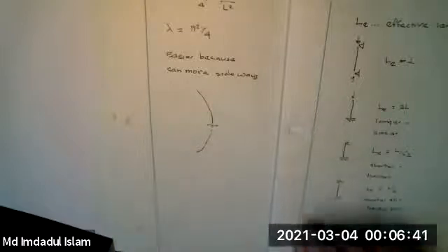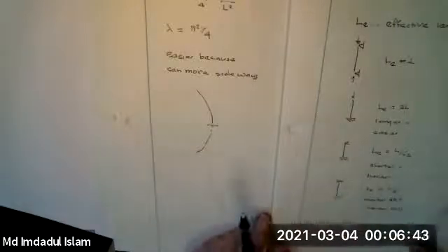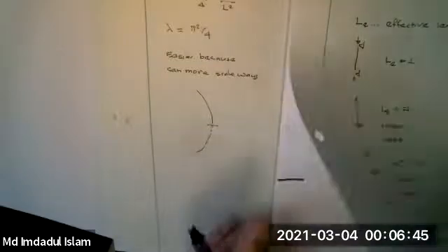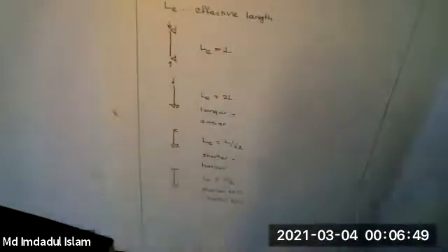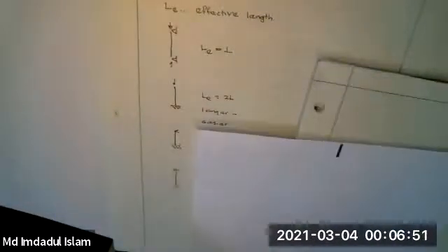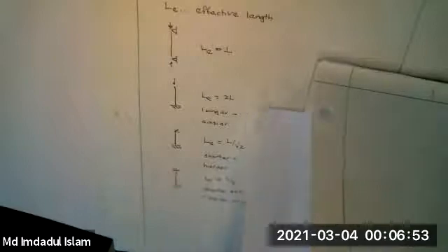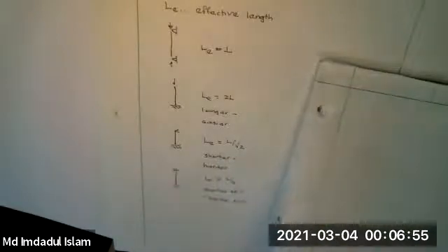Well, let me get started anyway, talking about short columns. There was a question about this earlier. When you get short columns, you start to yield. They have two competing mechanisms, whether they're going to buckle or yield.